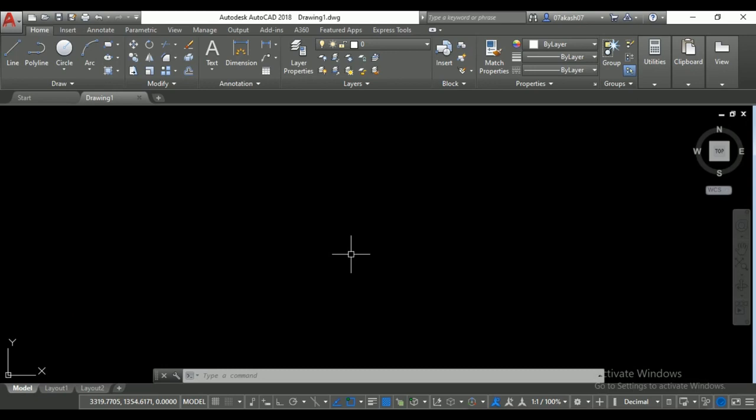So our next command is nshot. I believe it will be a new command for AutoCAD Advanced. Nshot is mostly used for animated view or motion view of any sketches in AutoCAD.